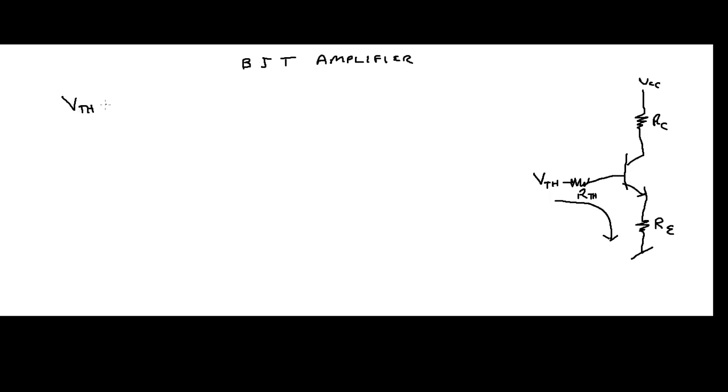You're going to subtract the voltage across your Thevenin resistor. You're going to subtract your voltage from your base to emitter. So remember, we got a voltage drop here, we got a voltage drop here, and we have one more. Voltage drop across RE. Get it? That must equal 0. It has to, right? Because you're ending up right here at ground.